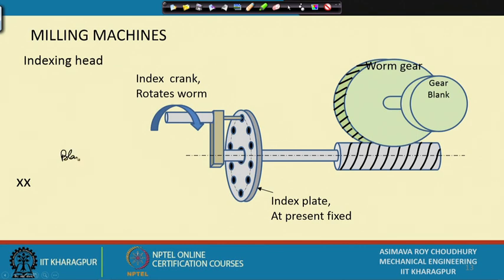Blank and crank. Crank means this handle which is moving round and round here. So, if I have to move by 1/4 of a rotation, I must be moving 40 by 4th of a rotation. Remember, 1 rotation, 40 rotations; 1/4 rotation, 40 by 4 rotations, unitary method. So, 10 rotations. This is the simplest one. Okay.